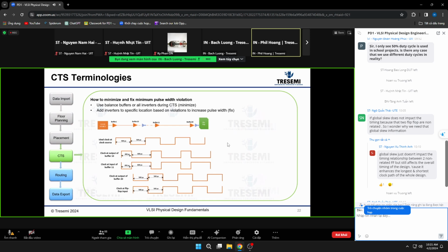Yeah, think of physically how clocks are created, right? Typically, it's by having a crystal oscillator or an on-chip phase lock loop. So you cannot just create them, and if you create multiple clocks, how are they generated on the chip, right? When you create multiple clocks, you're just creating virtual clocks, not physical real